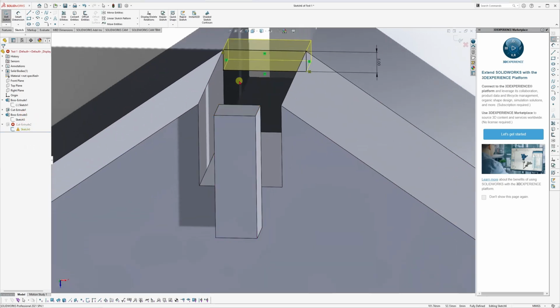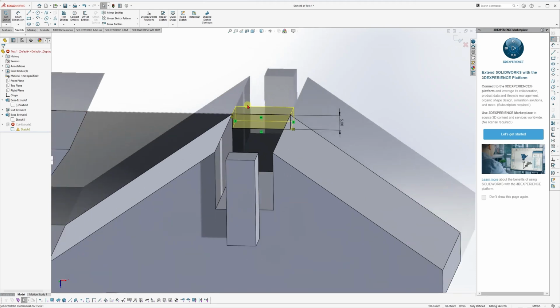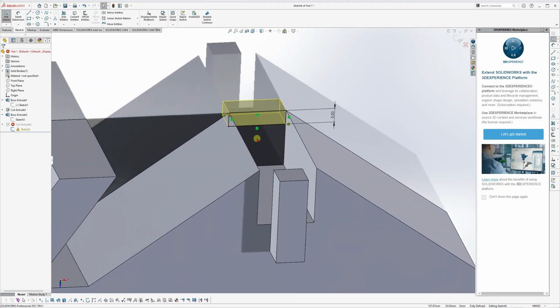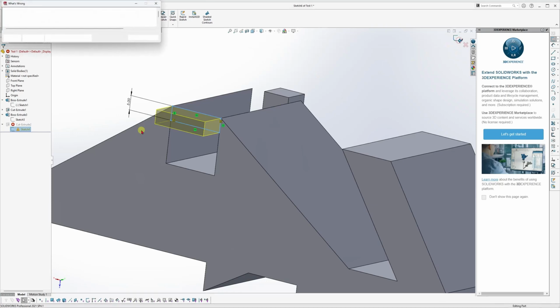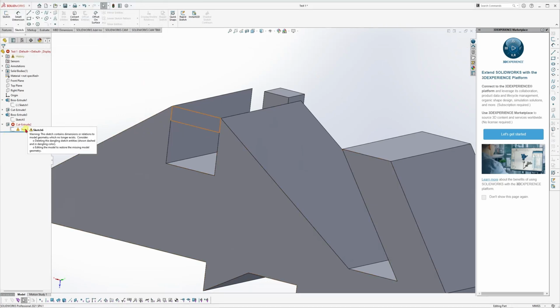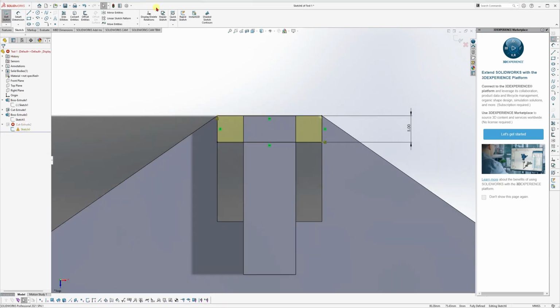Oh, this one is actually another 3D that is dependent on that part that I deleted. That's why it errors out. So now if I want to put it back, I have to edit the sketch, and as I mentioned a while ago, you have to press this and see those relationships that have errors. Okay, delete and then delete.